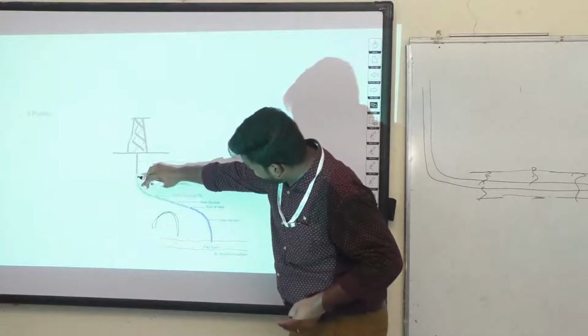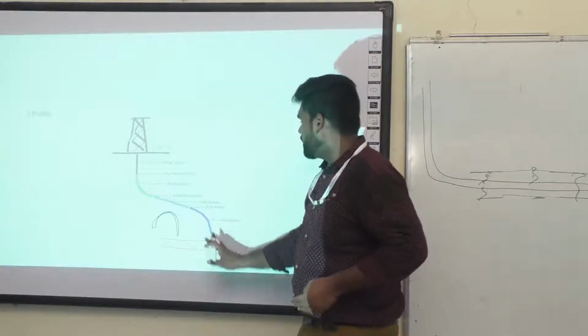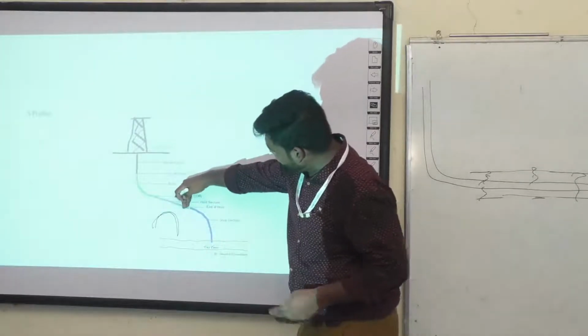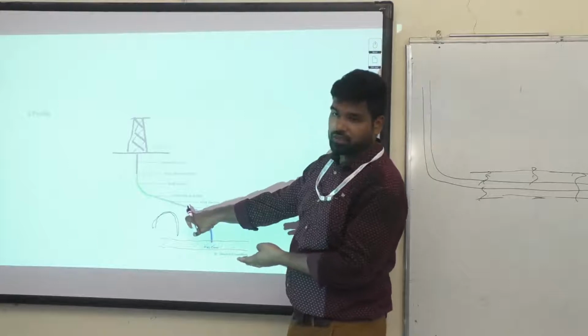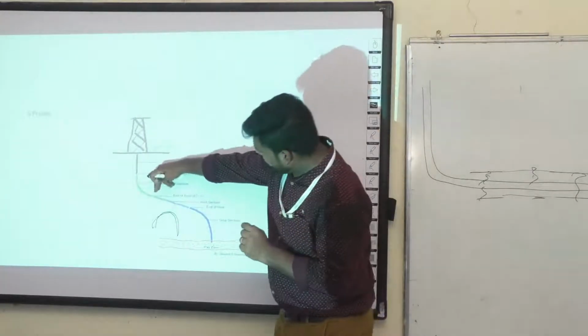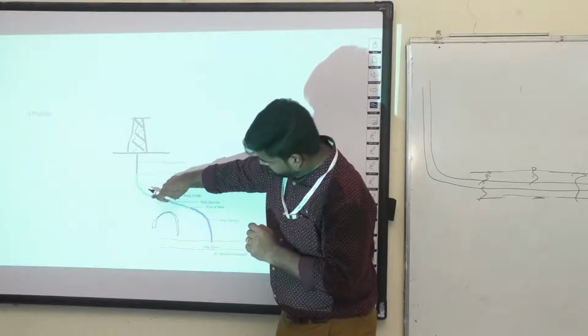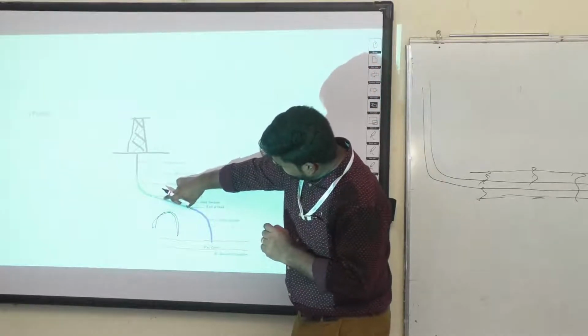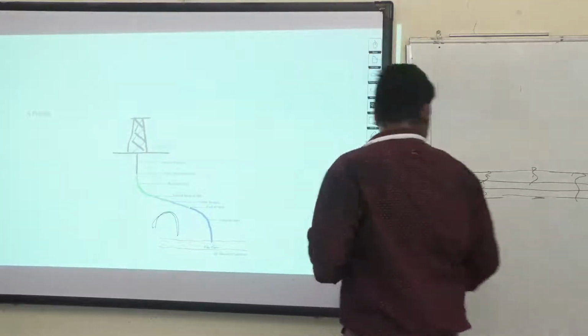At that time, I'm going to come like this, and then I'm going to drop the angle. What is this drop section? I'm just going to decrease the angle at the end of the hold section. Your end of hole will be at the same angle as at the end of build, right? So when I come here, I will drop the angle, which is called the S profile.